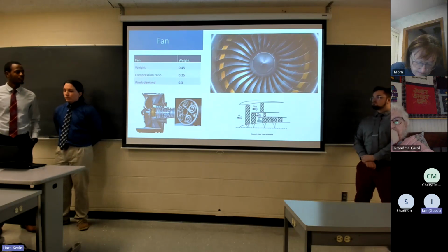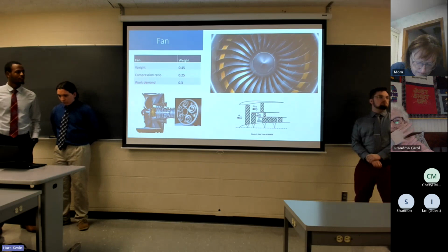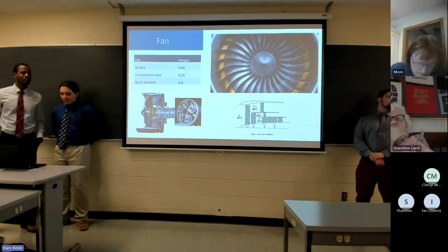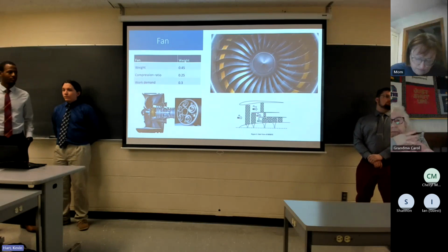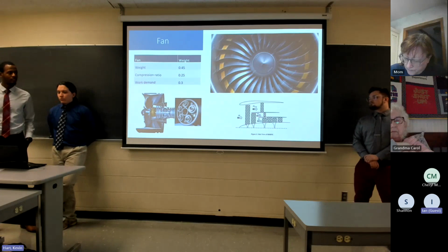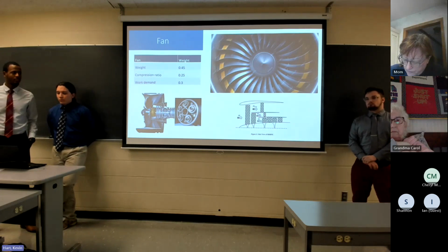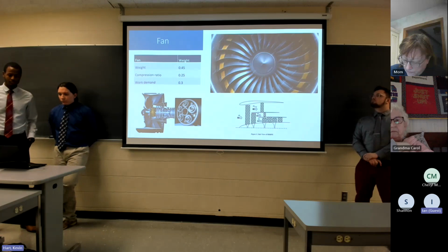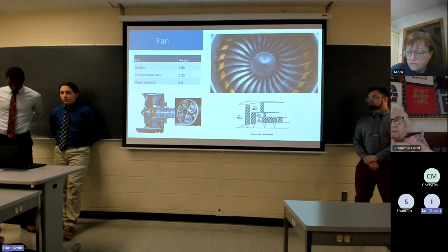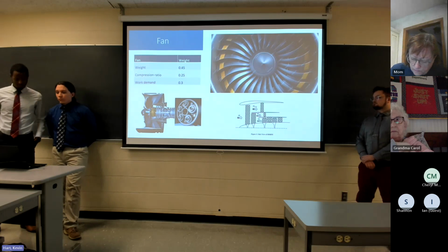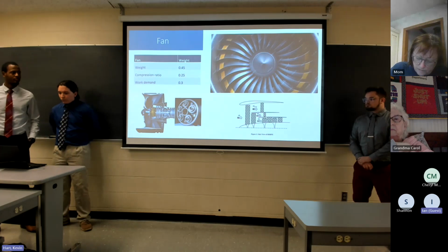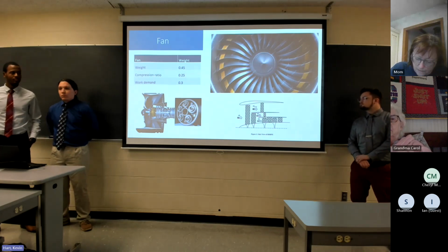A couple of designs that we looked at was adding gearing to the fan in order to run the turbine spool and the spool of the fan itself at different speeds, so as to reduce any stagnation losses due to the fan tips going sonic. Another design we looked at, which is right here on the right, is a double bypass fan, which allows for one bypass flow through a slightly smaller nozzle and then another bypass flow through a larger nozzle to allow for more work output.